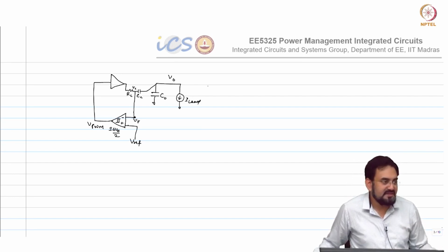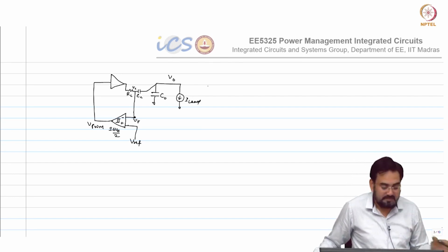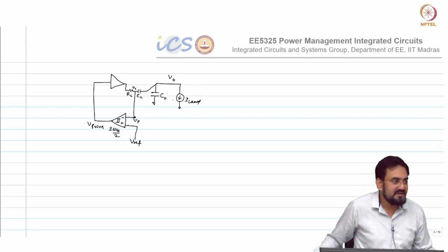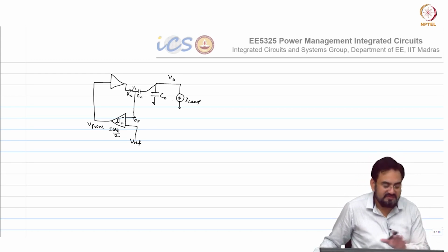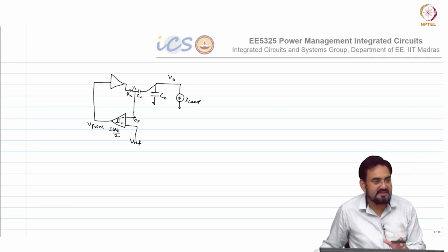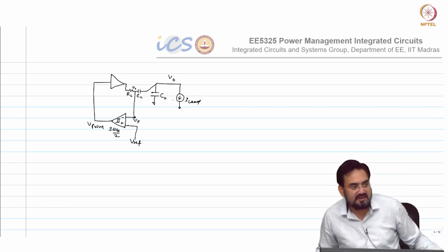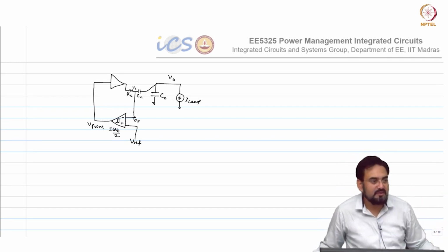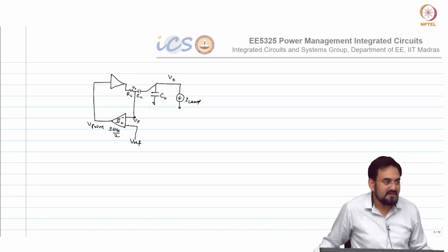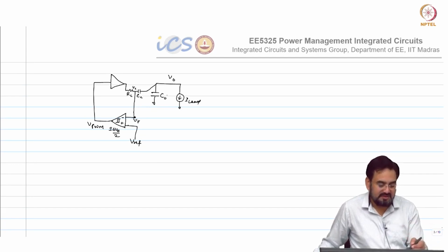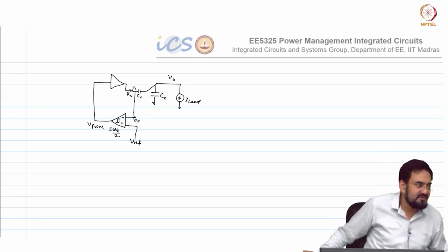So, in terms of frequency, there is no change as such, because your RC time constant is defining the frequency, correct, and you are only looking at a ripple component. So, let us say forget about the regulation, then in terms of frequency there is no difference between this and whether you have the inductor or not, or whether you have a feedback loop, unless your component which is coming from the output is significant compared to this ripple component, only then it will start affecting the frequency.